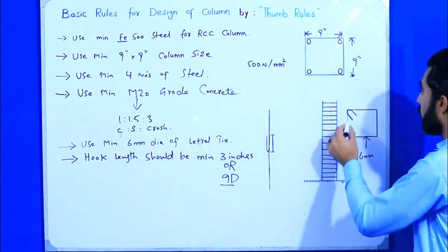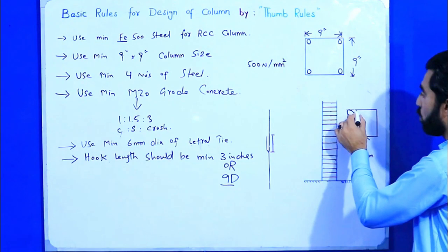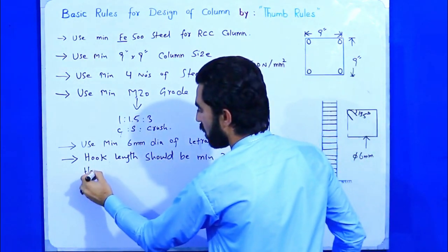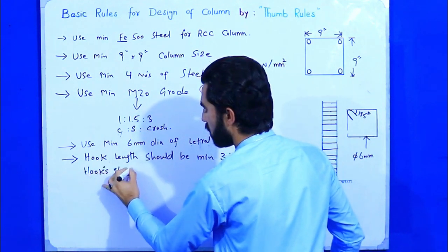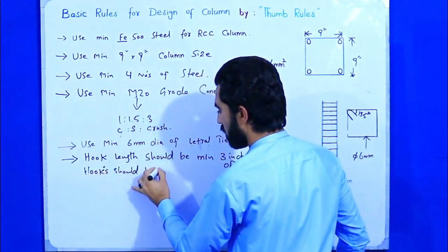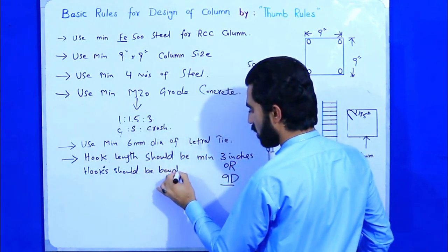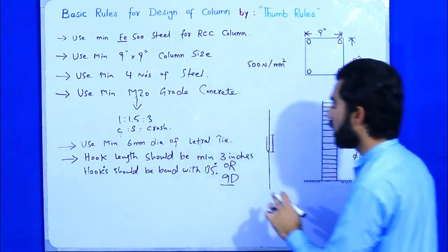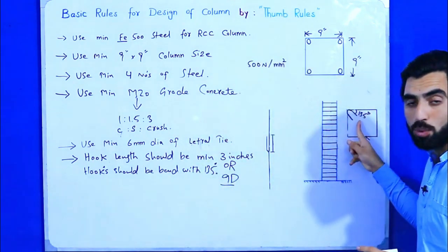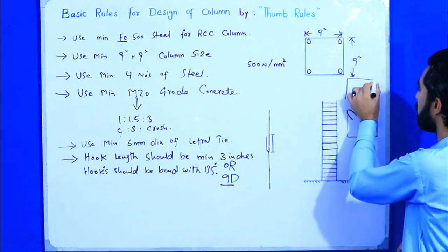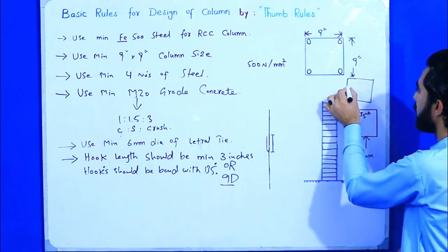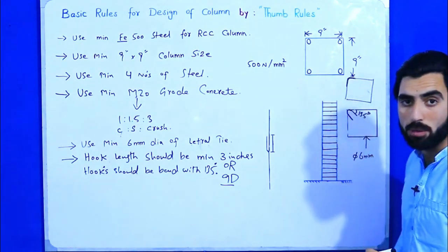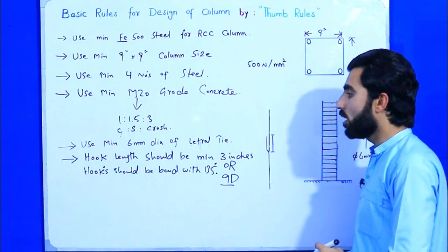You can see also the hooks are bent with 135 degree. This is very important, that the hooks should be bent with 135 degree. If you do not bend the hooks like this, you will face more problems in its structure design, right?